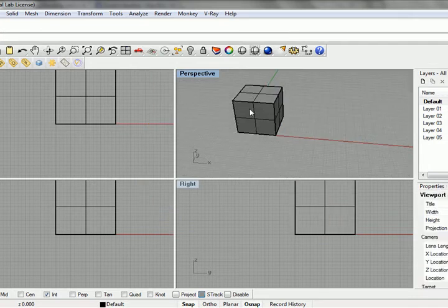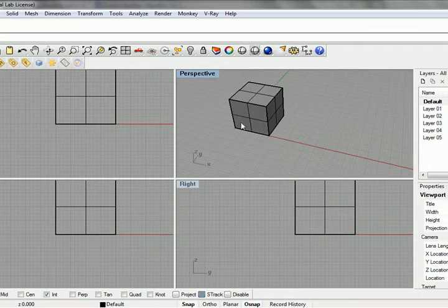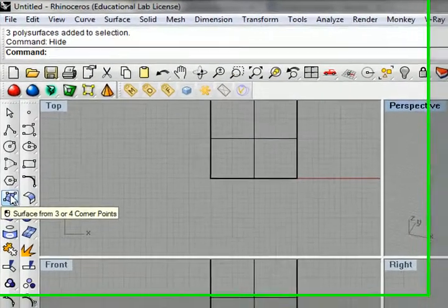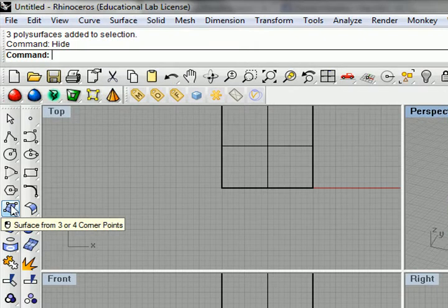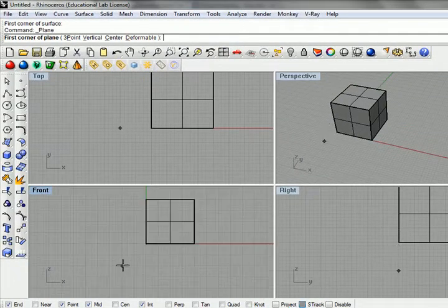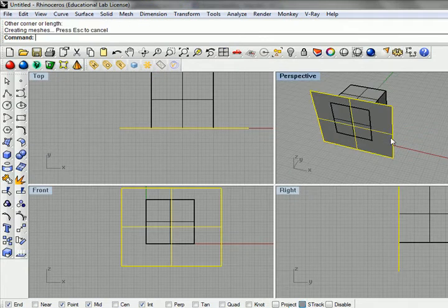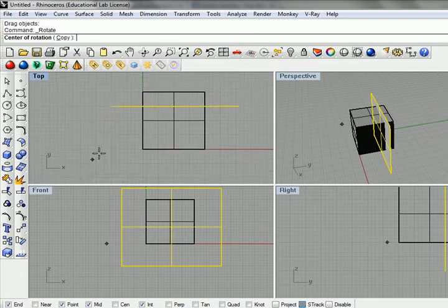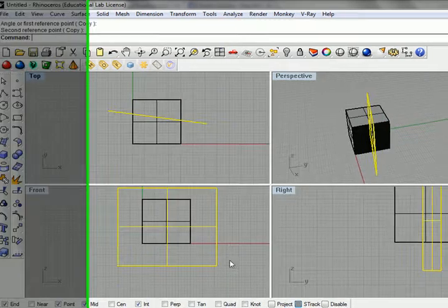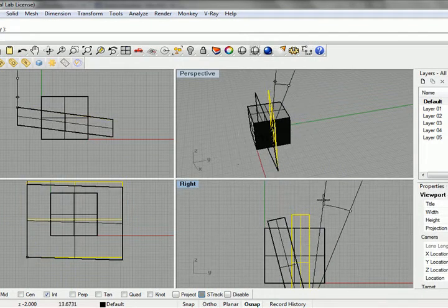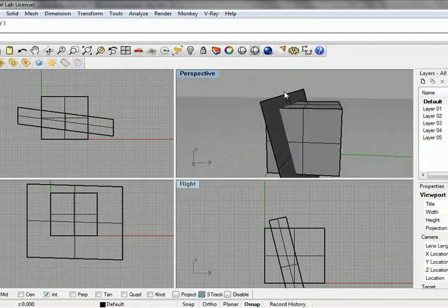I'll show them afterwards. So for splitting, in order to create a successful split, we need to have a set of geometry that completely cuts in or bisects the geometry here. So I'm going to go ahead and create a surface through here. And this doesn't have to have any specific orientation. We can go ahead and rotate, and I'll disable my snaps here so I can do this sort of freely. All right, so as we start to look at this, we can start to use these.